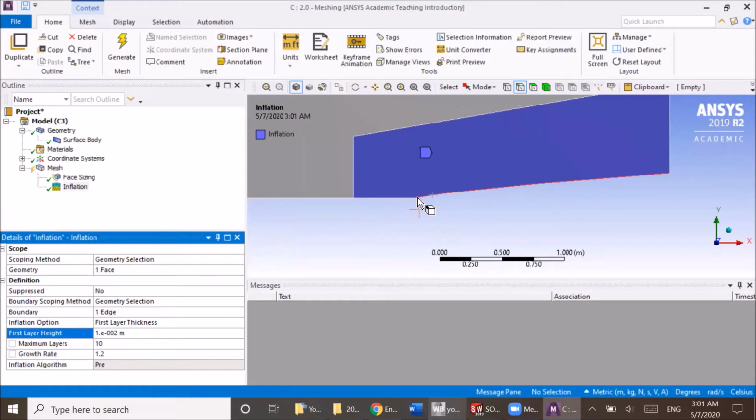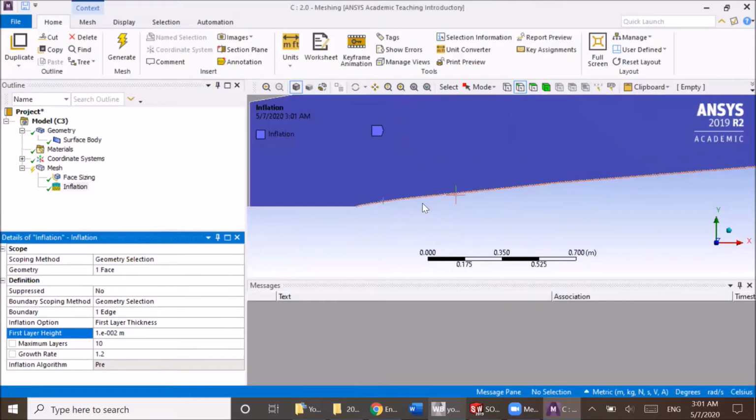So it is very important that you refine the mesh near your area of interest, just because when you import the geometry in the ANSYS FLUENT, it forgets what the actual geometry looks like and just remembers what the mesh looks like. So just be aware of that.